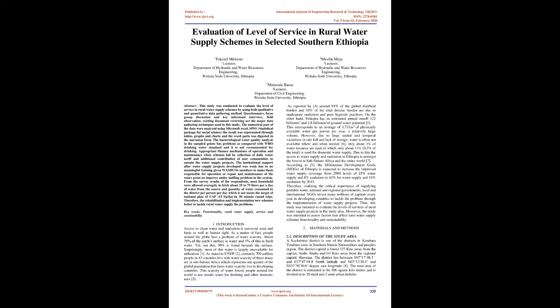The bacteriological water quality analysis in the sampled points has problems as compared with the WHO drinking water standard, and it is not recommended for drinking. Appropriate finance mechanisms for operation and maintenance when schemes fail are the collection of a daily water tariff and additional contributions of user communities to sustain the water supply projects.